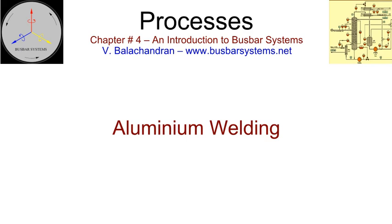TIG welding is generally limited to thin sections up to 3 mm, 1/8 inch, while MIG welding is carried out for thicker sections. Because of the low melting point of aluminium, preheating is not required for MIG welding unless the welding is being carried out under low ambient temperature and the sections are large.